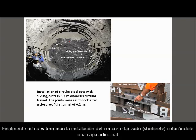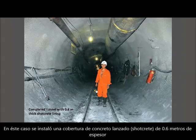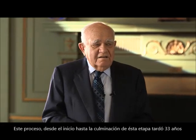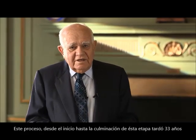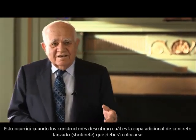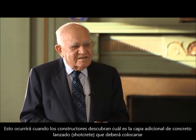and you complete the installation of shotcrete, and you put another layer in, and you end up with a tunnel which is now completely lined, in this case with 0.6 meters of shotcrete lining. And you might need to come back and put another lining inside that for long-term stability. That process from beginning to end to this point took 33 years. There's still a few years left. It's not in operation yet, while they figure out what additional lining has to be placed in there.